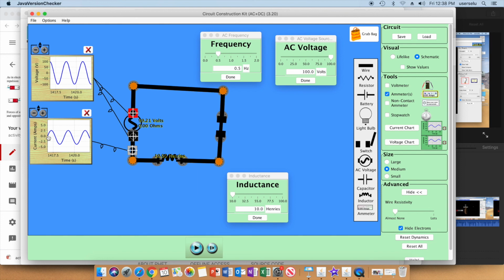So what an electronics engineer would say is that in an AC circuit with a coil involved, the current trails the voltage. And by what measure does it trail the voltage? 1/4 of a wave, which if you relate a wave to 360 degrees, would be 90 degrees. So a coil current trails the voltage by 90 degrees.